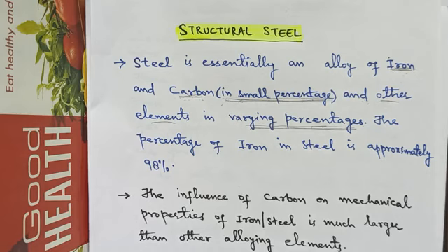However, by alloying chromium, nickel, molybdenum, vanadium, etc., the tensile strength of steel can be increased while retaining the desired ductility and hardness. That is, alloying chromium, nickel, molybdenum, vanadium, etc. permit tempering at higher temperatures, which actually generates better ductility at the same strength and hardness.